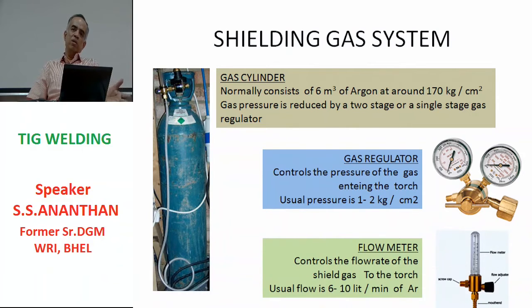The cost of the gas cylinder also increases according to the purity, and based on the requirement for the product, you choose the gases. For example, for welding nuclear reactor components, one goes for very high purity or ultra high pure gases. Or when one welds ordinary carbon steel for a power plant requirement and a refinery requirement, a welding grade pure argon gas is sufficient, that is 99.95% purity is sufficient.